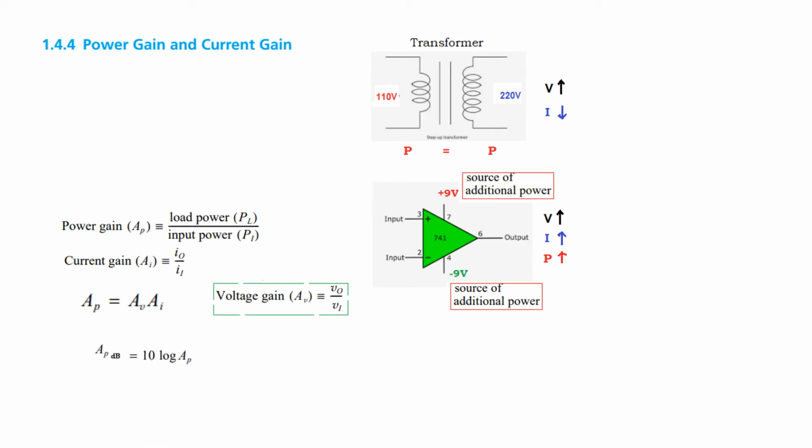Now we can write all these gains in terms of dB, which is called decibel. It's a measurement tool, or a number, for measuring power. The basic definition is that whatever the power is, if we take the log of that power and multiply it by 10, then we get the value in decibel, dB. Now that is for power, the gains in decibel.